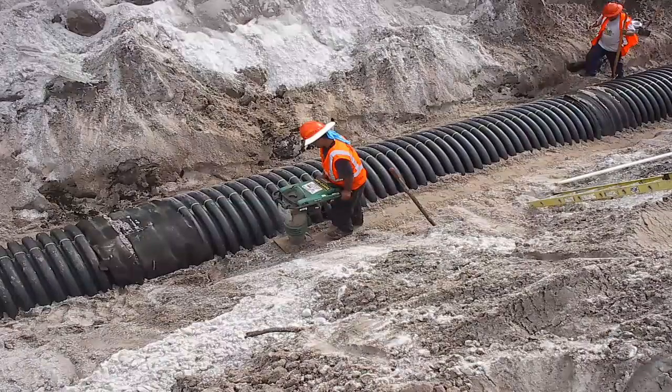So here's a picture. I just wanted to show you what it looks like if we're installing on the side of that pipe. We want to make sure that we're installing on both sides. We're compacting on one side and then the other. We don't want to get too high on one side because then we've got other issues there as we compact it. But this is a good picture of how much space you need on the side of that pipe to make sure that we are meeting adequate compaction.